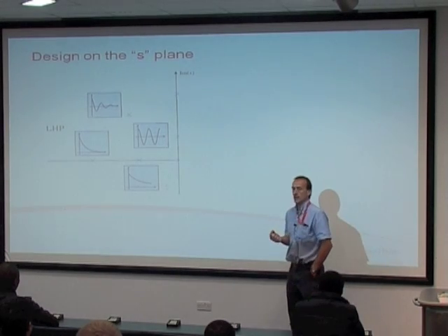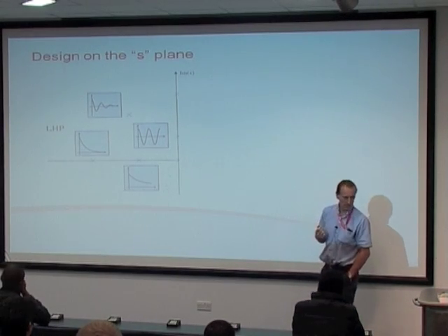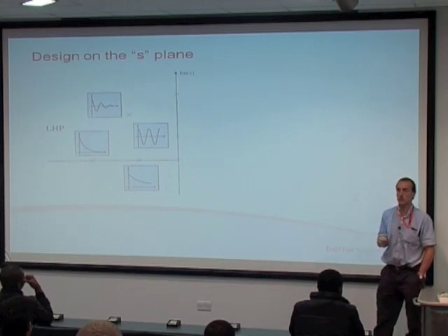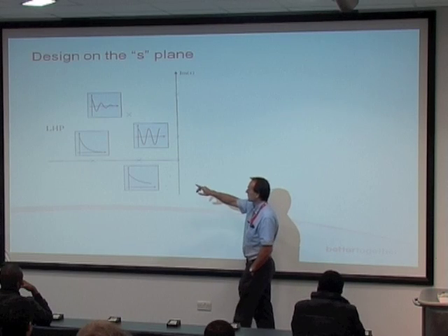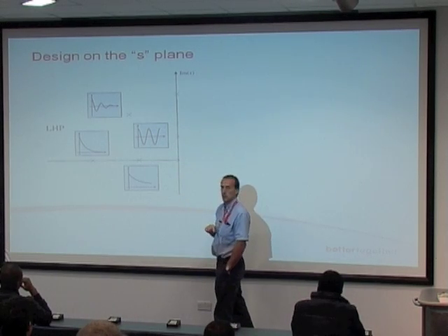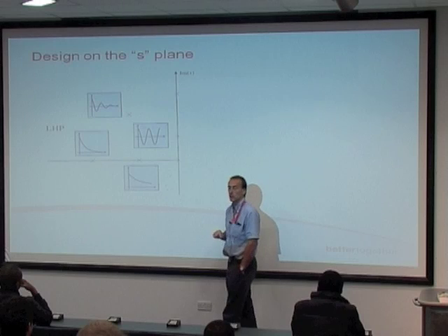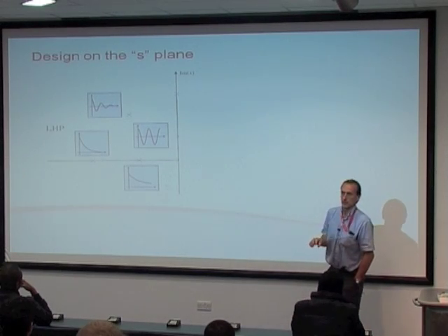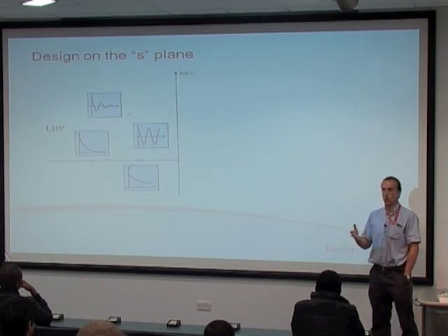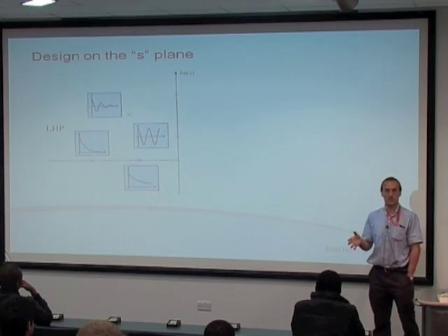What we actually get for that imaginary part is not omega n at all. If I was to read across the coordinates from my complex pole just there and look at the imaginary number, what that would tell me isn't omega n. It would tell me about what I call omega d, the damped natural frequency.